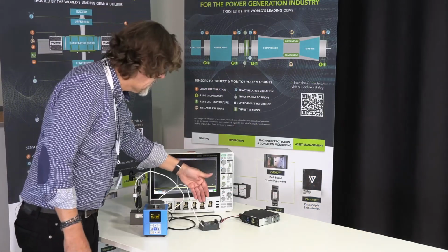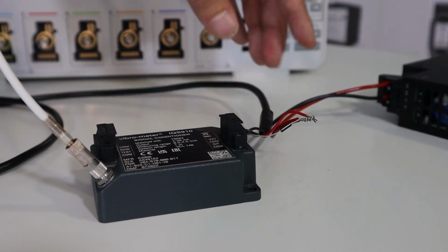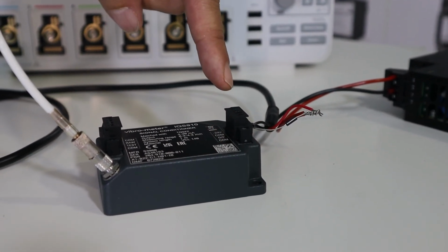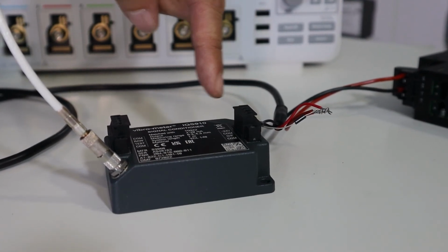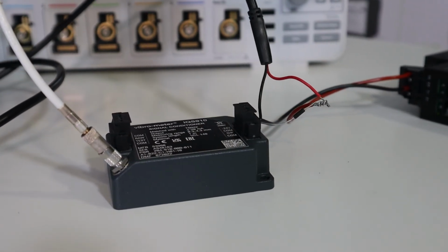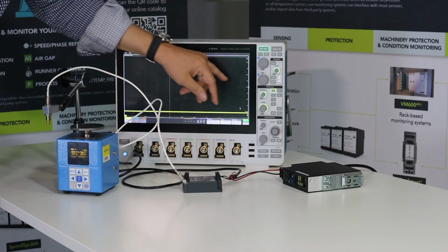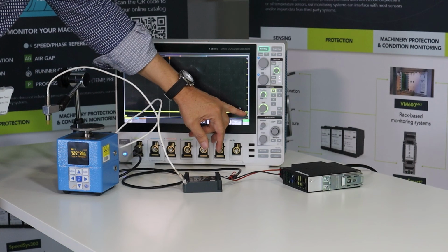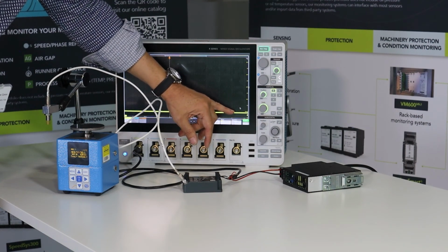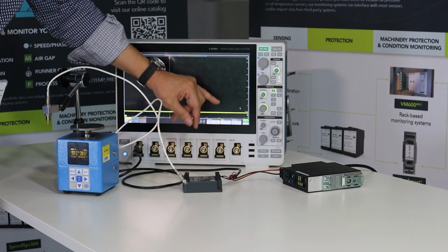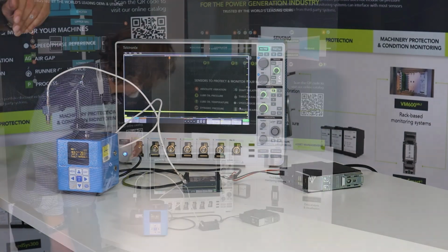Here is the IQS 910. So the IQS 910 is powered between 0 and minus 24 volts. But as it's a current output, we put in place a resistor in order to have a voltage visualization of the signal. So here we can see the signal, which is a little bit above 0, which is in fact the representation of the standby current, which is roughly above 4 milliamps.